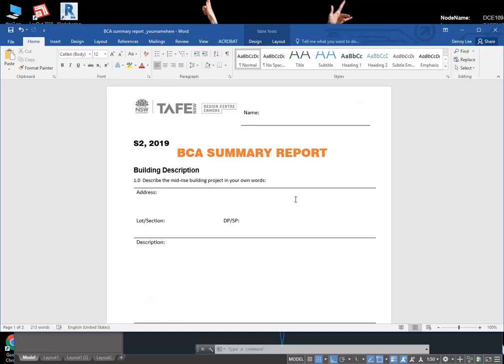Yes, and now, what you need to check there with those open spaces is that you've got the fire separation between the compartments in those open areas too. So where's the open space there? Okay, so are these different units? No, that's all one unit. So they go in there, that's the front door, and go through the open space. Is there a unit above this?